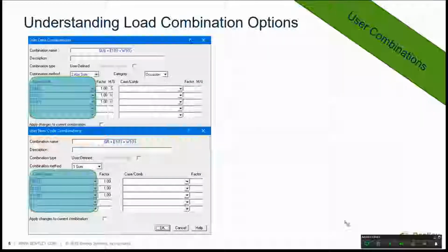Next, the user must enter the name or names of the contributing components of the current load combination that's being created. This can be an existing load case, a combination, or a predefined stress category. The predefined stress category represents the maximum of all of the stresses from combinations that are defined to be of that category type. The maximum stress is added to the stress resulting from the other contributing components. Predefined stress categories are entered using parentheses around them, such as the sustained case that we see in the top dialog box here. There are some restrictions on the contributing components.